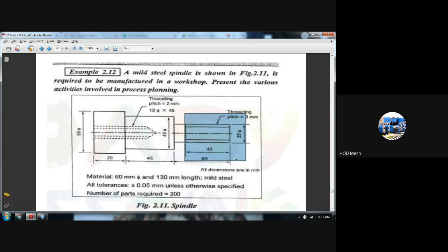அப்போ 2-3 வேரியேஷன்ஸ் வரும் இது பண்றதுக்கு depending upon the feasibility of work that has to be completed. எதுக்குன்னா this end you are having outer threading. அப்ப outer threading இங்க இருக்கிறதுனால உங்க ஒர்க் பீஸை இங்க ஹோல்ட் பண்ண முடியாது. So always a process planner will look for completing this task of external threading as a last step, provided there is no space for holding the workpiece when the workpiece is rotated.